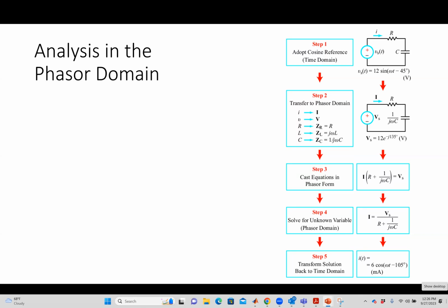This result here says I equals V over R plus 1 over j omega C. Basically, it says that the phasor for I, the magnitude and angle are whatever these are, and I can take the value of the magnitude and the angle and slap them right back into the time domain function. And I've gotten away with getting the steady state result without doing all of the grungy differential equation stuff, which is ugly if we do it that way.